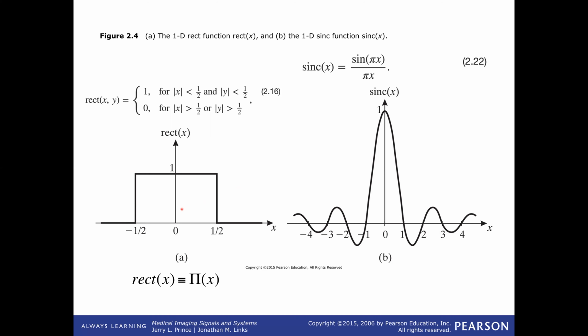And what's very interesting to note is what does that do to the frequency spectrum, in the Fourier space of that function? Obviously, it changes it because you've added this sort of discrete cutoff. So it's good to know the Fourier transform of this thing. You should have it in your head. And the Fourier transform of a rectangle function, when you take it over to Fourier space, is called a sinc function.